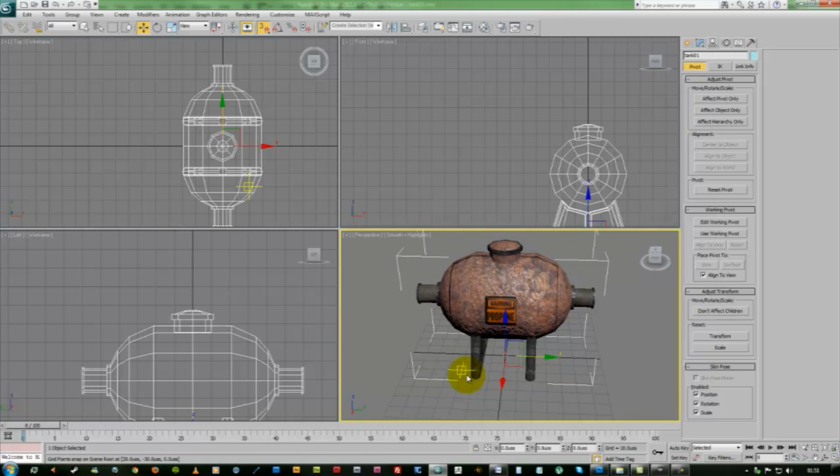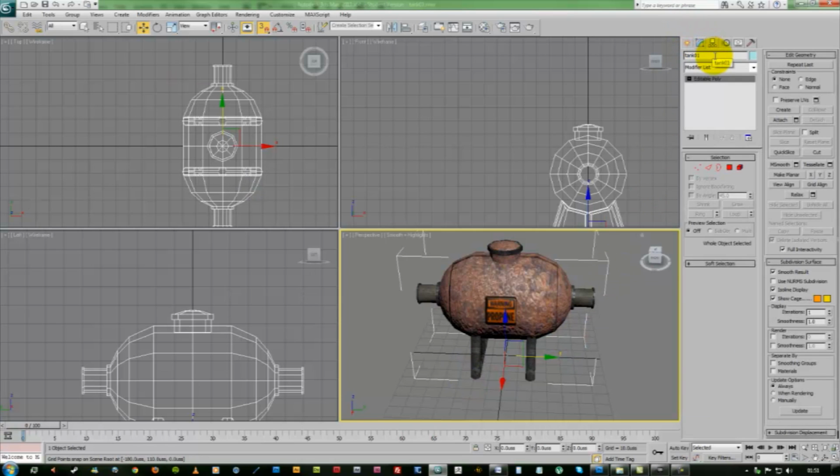Naming of the model is important to make sure you're using the correct mesh within the engine, which can relate to its custom collision data created in earlier tutorials. So make sure, once you have named the mesh, the collision mesh has the same name, but beginning with the pretext UCX underscore. Okay, so we have under here, under the Modify tab, the actual original mesh's name as Tank01,